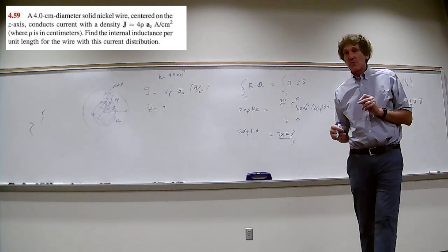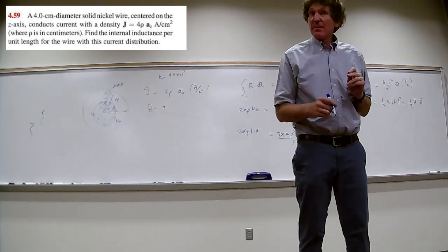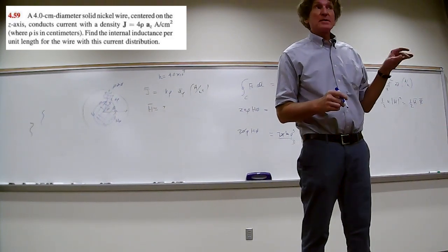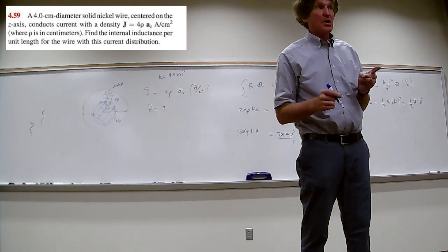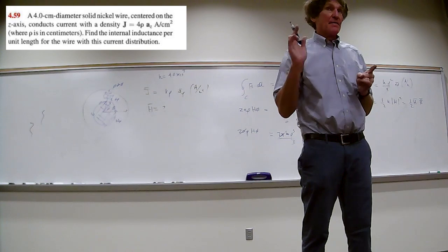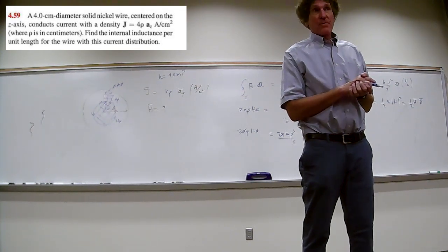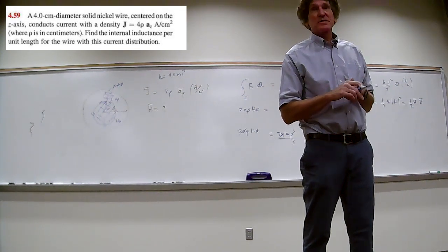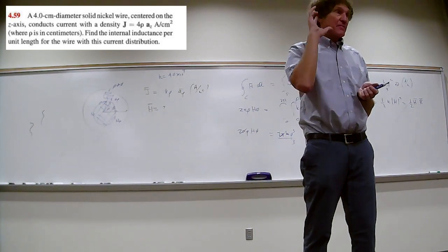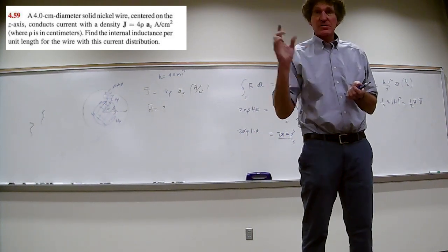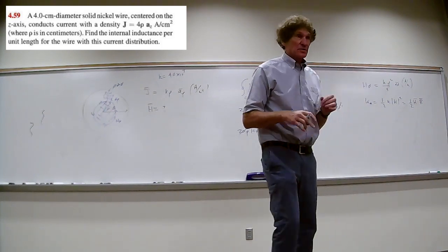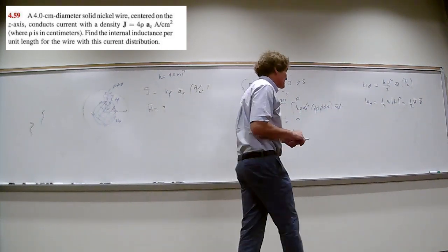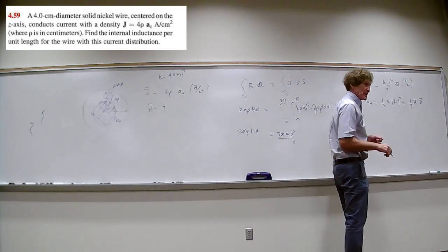It means it's a 3x3 matrix. And then it wouldn't be just mu times the magnitude of H squared. You would have to do the full dot product, mu times H. And that's something that happens for very special cases, like in the ionosphere, where you have tensor permittivities and tensor permeabilities because of the ionization. That's a topic well beyond the scope of this class. This is standard. Go with me, class?